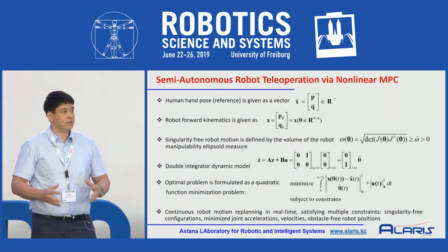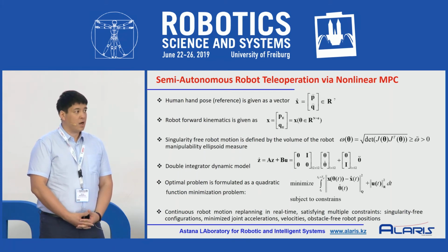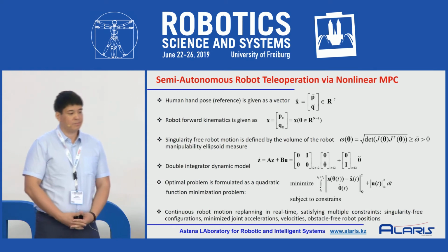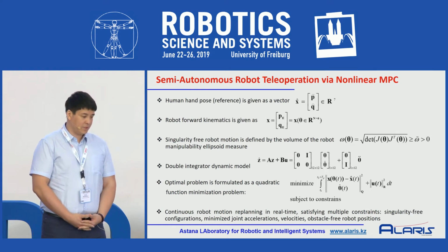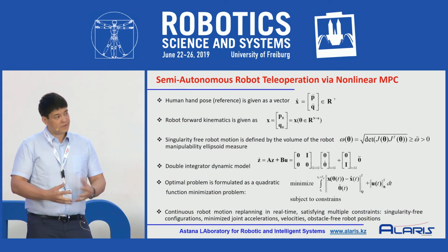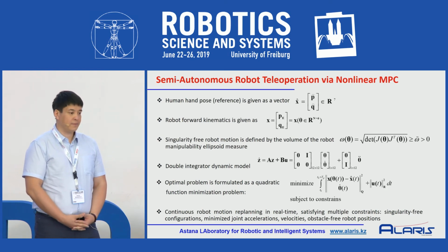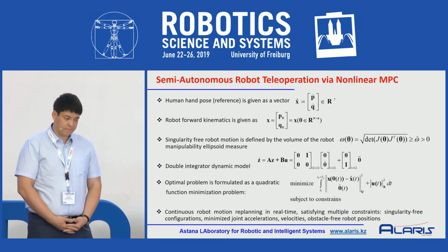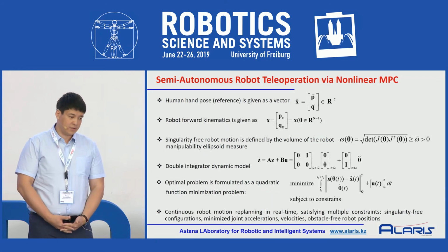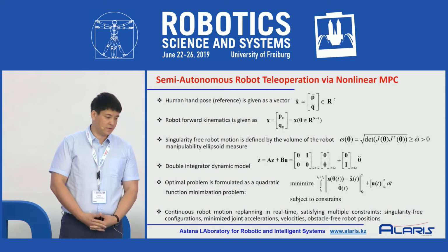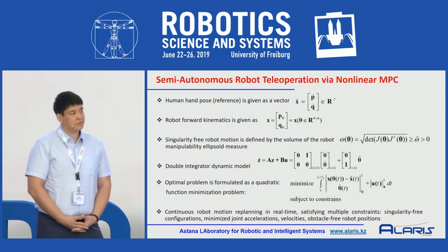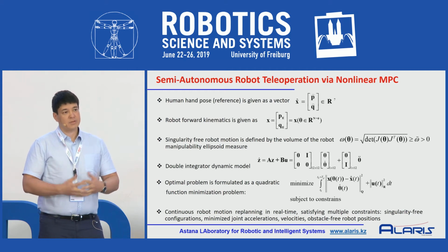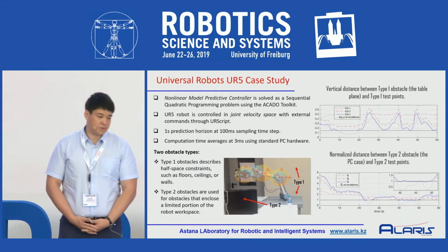We formulate our arm motion using quaternion algebra, for orientation and position, and the optimization problem we defined as minimizing the error between the human hand motion and the robot end effector position and orientation, and also we minimize joint velocities to generate smooth real-time robot motion.